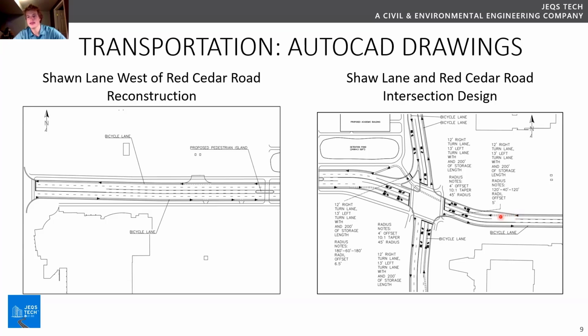The bicycle lane on the northwest region right here, as you can see by the laser pointer, is for bicycle safety. If we had it crossing just straight through, there would be a merge point of traffic, and that would be extremely dangerous for bicycles, as the oncoming vehicles are not expected to stop there. So we had that align with the pedestrian sidewalk, as the laser pointer shows, and that was a very innovative solution for bicycle safety.